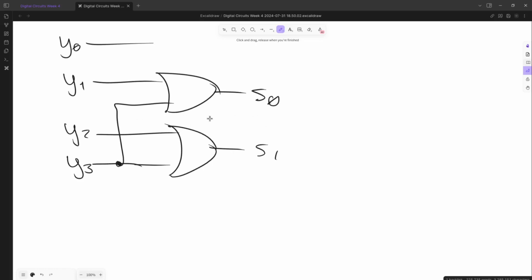And this would actually be very useful if you have, let's say, a selector with buttons. You have 1, 2, 3, or 4, and let's say you want option 1. You click on the first button, and this would be encoded as a binary representation of that. Or let's say you want the third option, you press button 3, which is Y2 in this case, and that would get you, well, 1, 0. It's a pretty nifty circuit. In fact, I think digital circuits are all nifty.